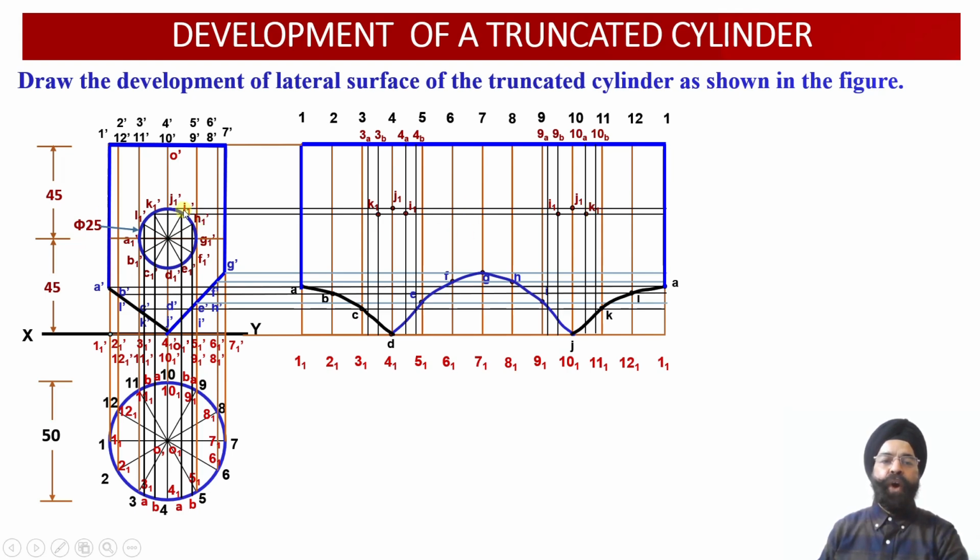Let us obtain I points over here. So I1 dash is the point of intersection of the cutting plane with, let us see which points onto the circumference. If I bring a vertical projector from point I, onto 9B point I will be located, and similarly onto 4A, I will be located. So I will be located on 4A and on 9B. Let us locate point I on 4A. We can check onto 4A the vertical projector intersecting with this horizontal projector, we have obtained the point I1. Similarly, it is also available on the rear side with the generator 9B, so point I will be located over here.